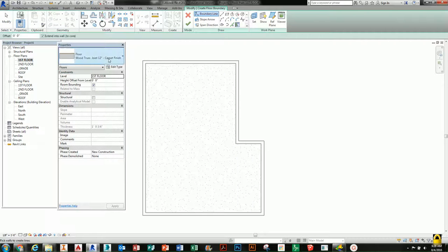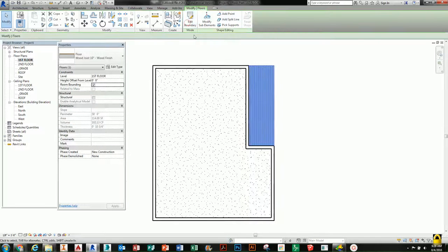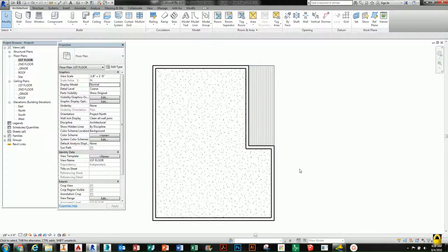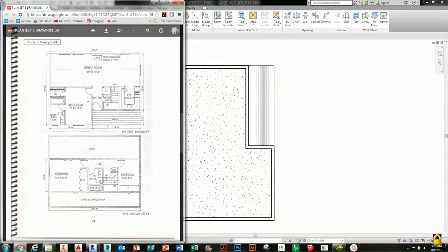Then I'll create my floor for the outside, which is wood. That's going to go from here to here, and then let's close that using a line. And we have our wood floor patio, our inside. And the next thing we're going to start doing, before we worry any more about the outside of the building, is laying out these rooms on this first floor, and then we'll talk about the second floor. But you've got to make sure your levels are right, or else these stairs are not going to make sense. All that's going to get confusing.